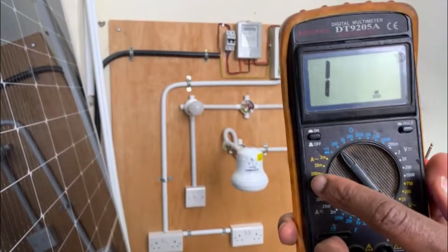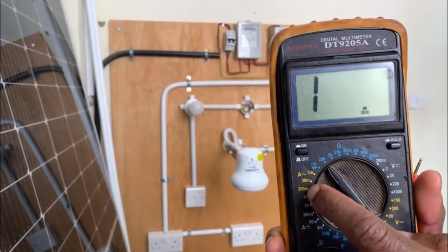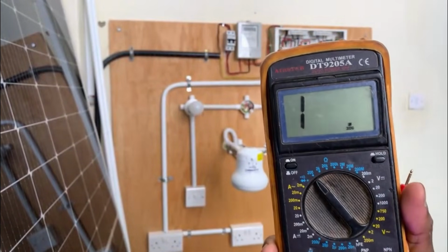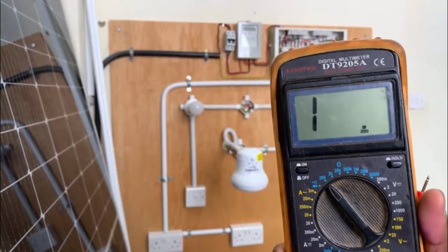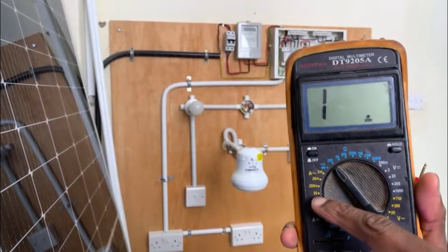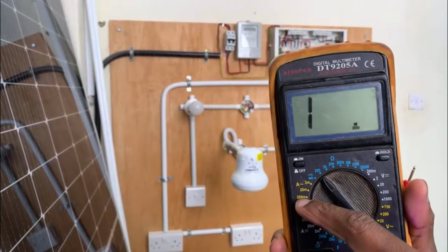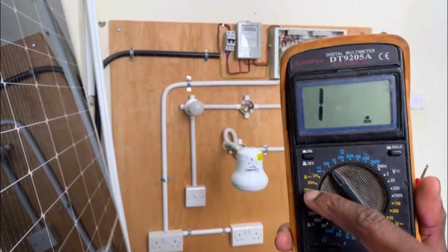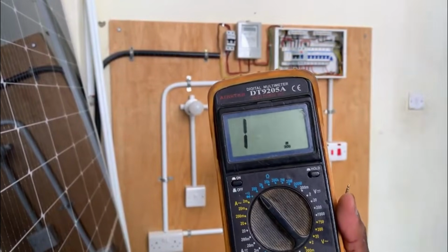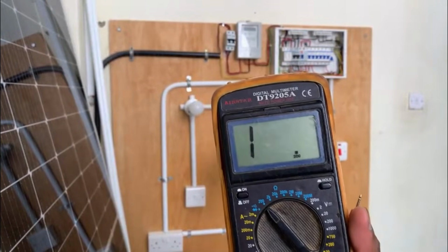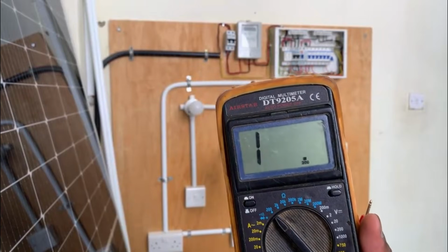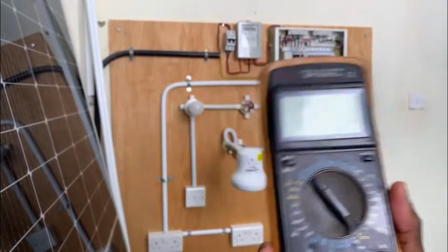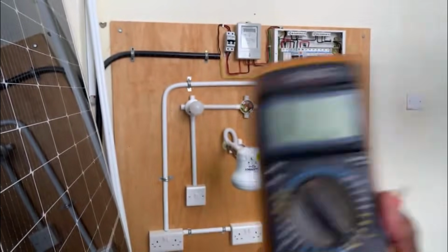I mean courses. We also have current, and this is AC current. When you see A and then that wave, it definitely means alternating current. You're measuring alternating current in terms of amperes. So here is amperes, 200 milliamperes, 20 milliamps, and so on. At this point here where we have white, we have direct current. If you want to use a multimeter to record current, you have to know that you will have to isolate that circuit, because you have to place the digital multimeter in series with that circuit.